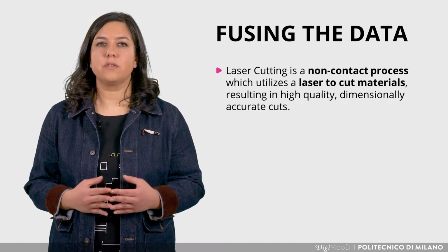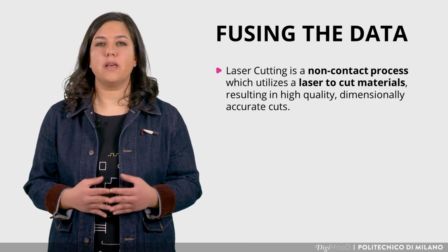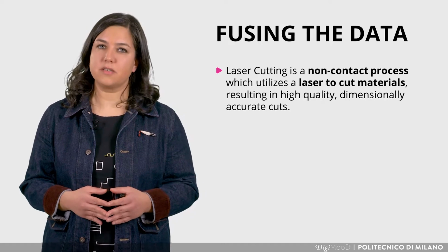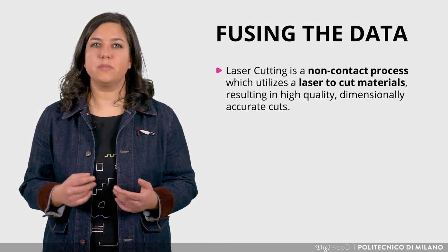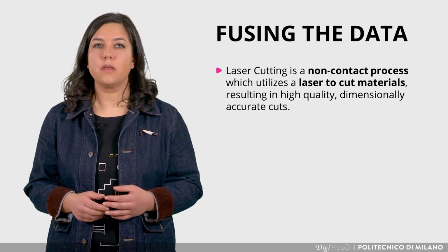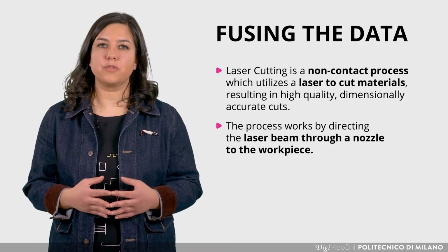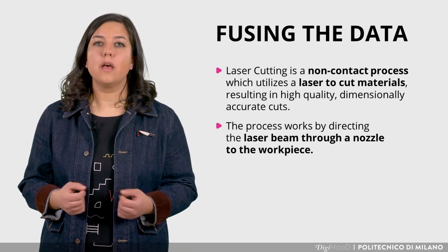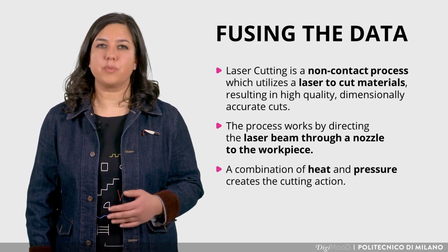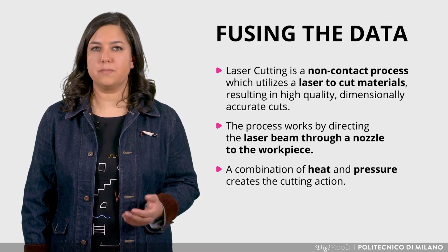Laser cutting is a non-contact process which utilizes a laser to cut materials, resulting in high-quality, dimensionally accurate cuts. The process works by directing the laser beam through a nozzle onto the workpiece. A combination of heat and pressure creates the cutting action.